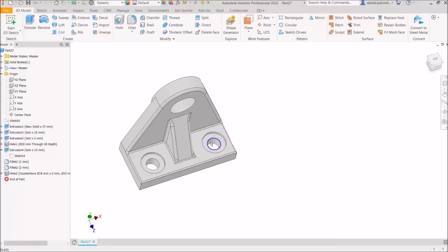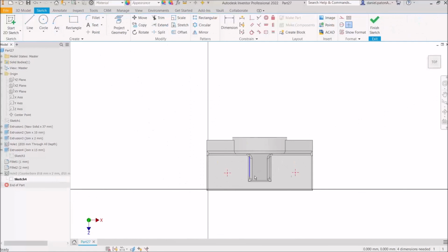Now these holes are not positioned, and we didn't create any sketch for them. But the hole command is clever and creates its own sketch in the background when you use it. So if we want to find that sketch that it's created, again, we look for the drop down, little plus next to hole. Find that sketch, double click on it, and we can go and edit it.